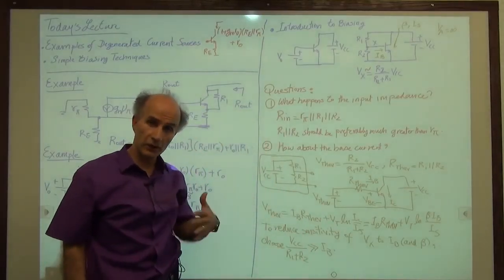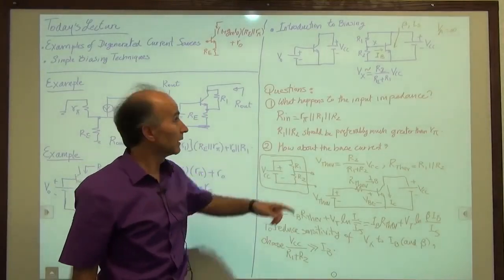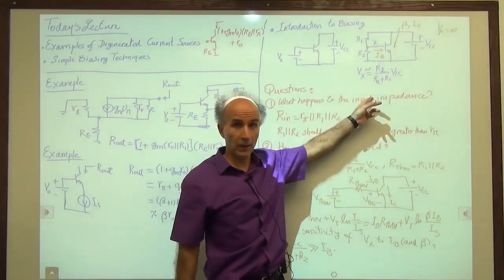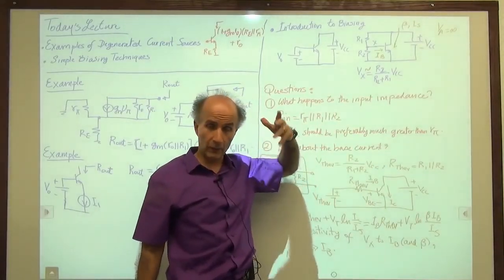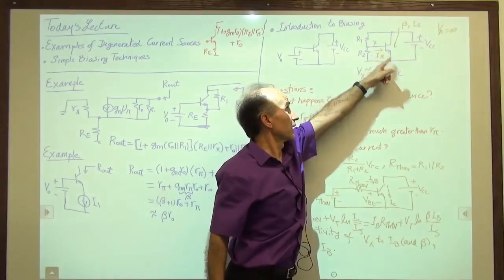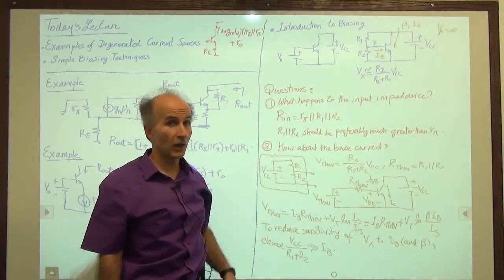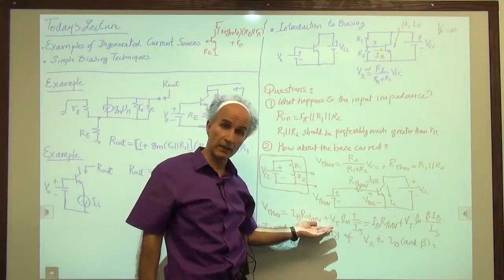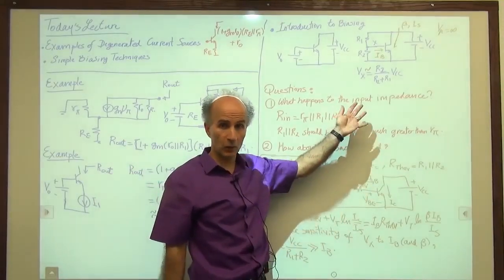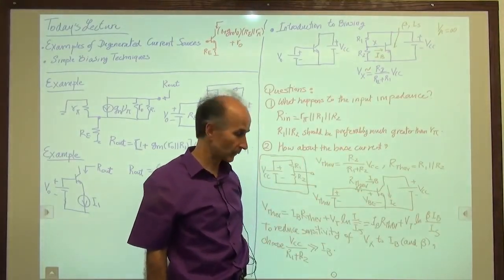Okay, so now if IB changes to some extent, Vx doesn't feel it. Vx is still approximately equal to this equation. So when I wrote this equation, my implicit assumption was that this current is much larger than IB, and this approximation holds. And this is not just for mathematical convenience, but actually it's good for practical designs because we don't want to be sensitive to the beta of the transistors.